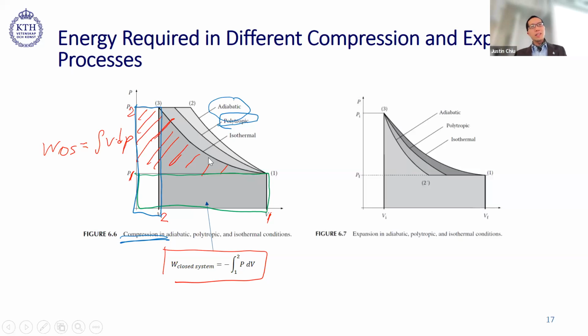I was thinking the other way around, that we generate heat and then we remove that heat. But here, adiabatic means that we contain the heat. The heat that is generated is actually heating up your air, or your fluid. So that's why it takes more energy to compress hot air as compared to cold air. That's also why you have interstage coolers for compressors, where you cool down at an intermediate stage between the stages.